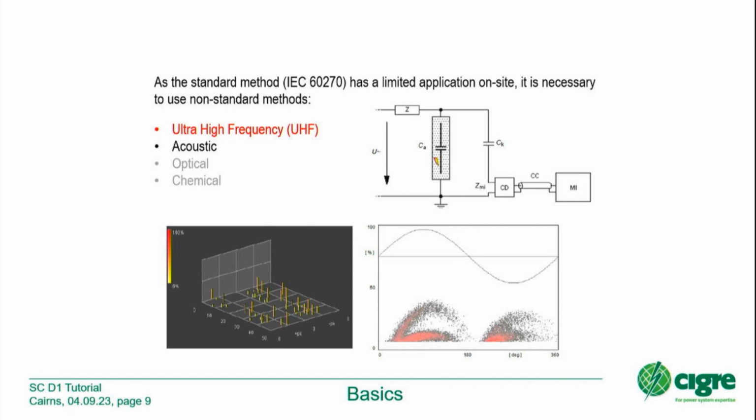Other point is you can try to do localization of the defect. So make time of flight measurement between these 2 couplers with the fast oscilloscope, and maybe you are getting 2 positions of the defects. And then you have to do maintenance, repair work for 1 and then the second, whatever it is.